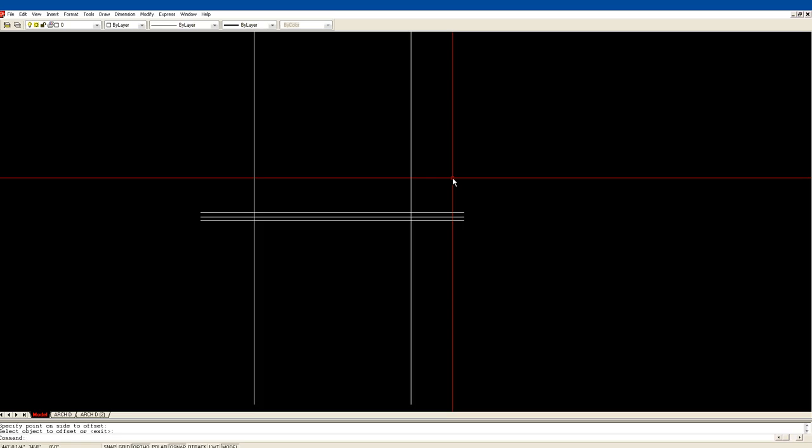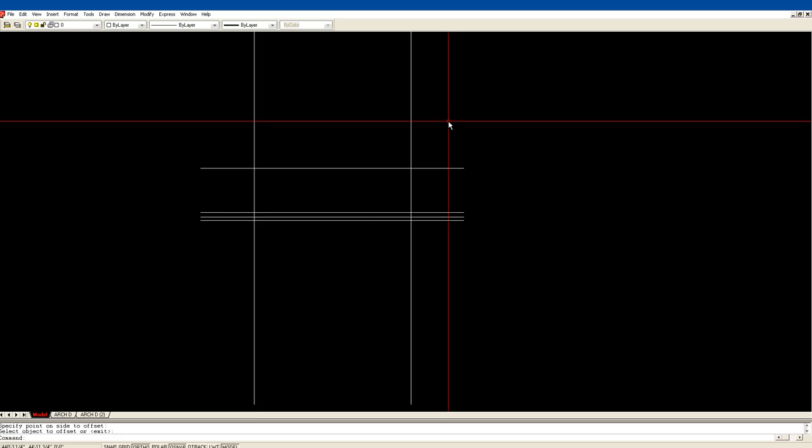Okay, now I'm sure we talked about it with this fellow. I'm not sure that I wrote it down, but I believe he wants 8 feet as a normal height on the main floor. And so offset 8 feet. If he doesn't, we can change it later. Again, it's something to ask him next time. Okay, so we've offset, that's the top of our main floor walls.